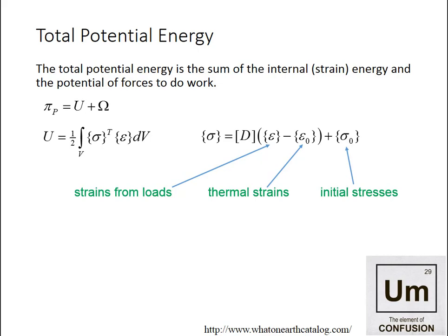I'm going to elaborate a bit on what we've previously talked about in these videos. The basic idea of stress is equal to the D matrix multiplied by the strain is generally true, but not true for certain cases where we have thermal strains present in the problem or when we have initial stresses. If we want to consider those two cases as well, we have a more generalized expression as shown here. So the thermal strains have to get subtracted off from the total strains that we have, including the loaded strains, and then the initial stresses need to be added on in order to have a complete expression for the strain present.